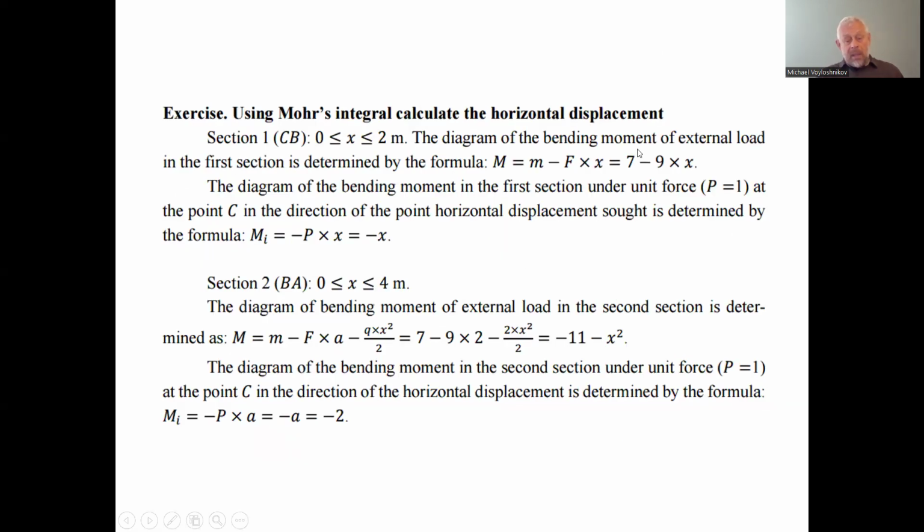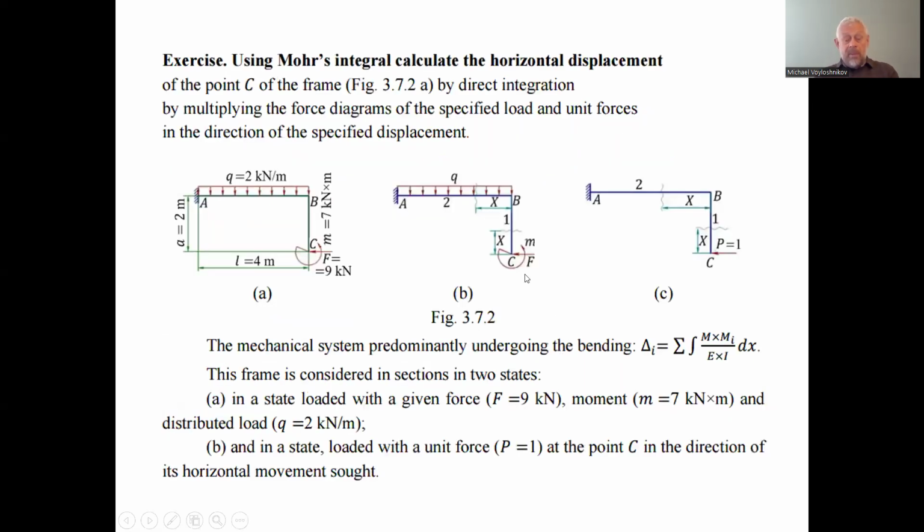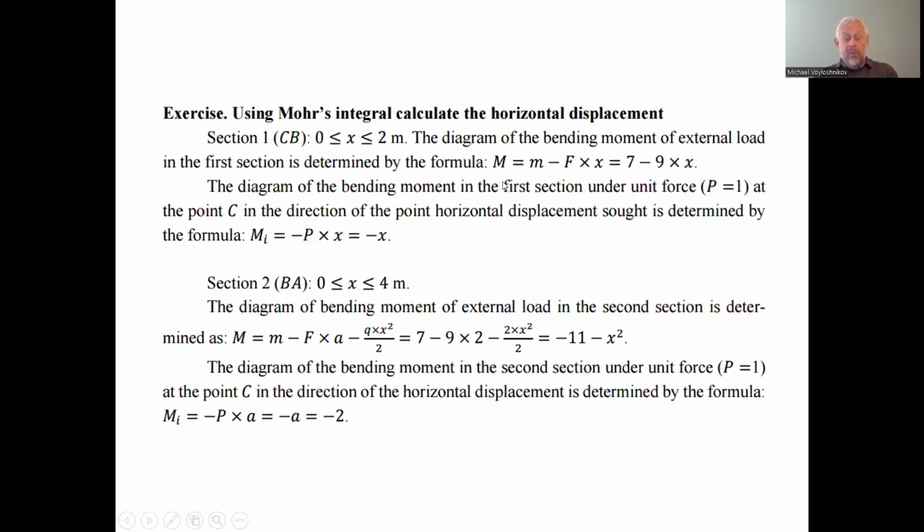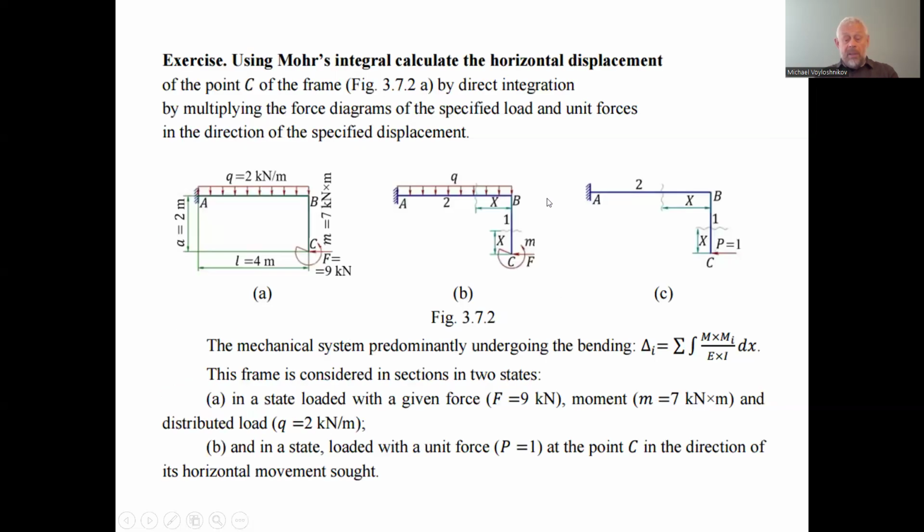as bending moment along section 1 will be the moment rotating this counterclockwise. We will adopt the counterclockwise direction of rotation as positive, and minus for force rotating clockwise. We consider rotation of any point of this first element by the assigned force or by the assigned moment.